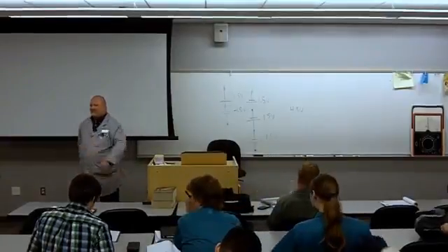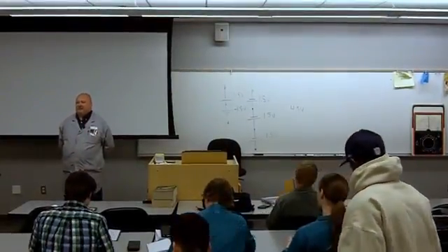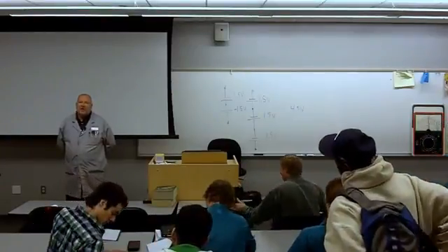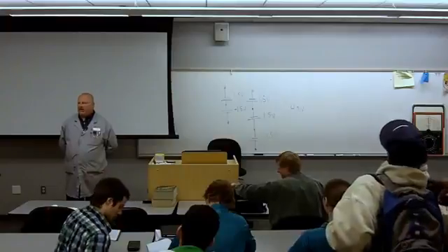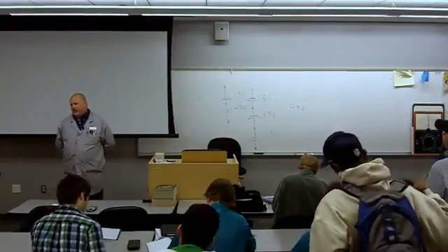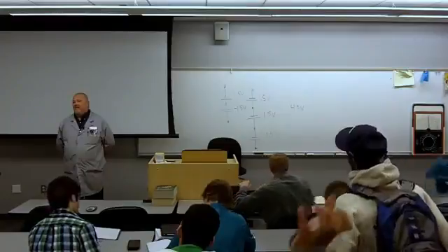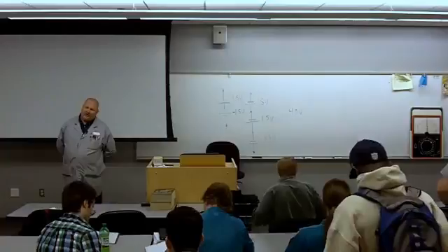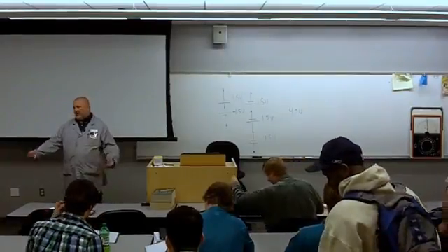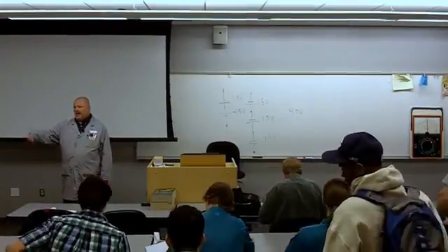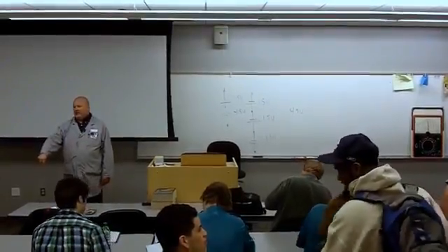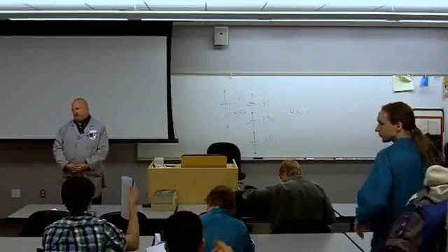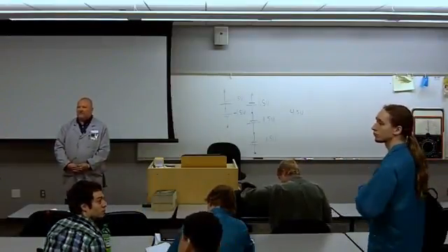That's cool. Question? How do you measure ground? It is measured in ohms. It's a comparative process of what you assume is a good ground, and you're basically comparing your unknown ground to that good ground. But there's an assumption made that by getting an 8-foot long rod and driving it in, that is providing you with an adequate ground. You need something else to compare it to in order for your assessment to be accurate.